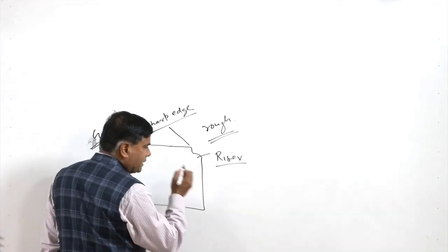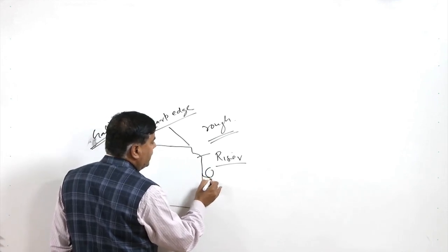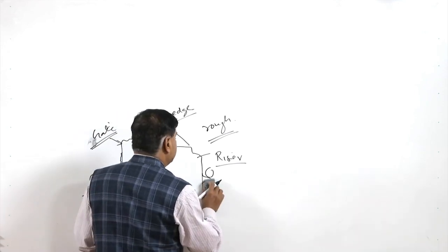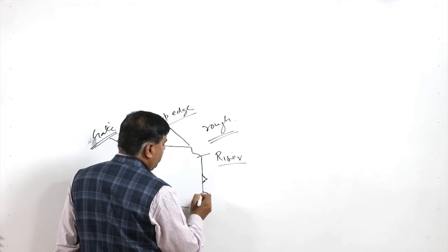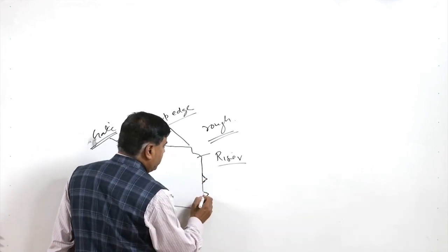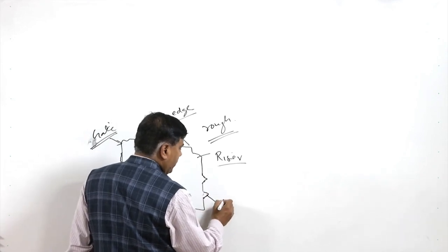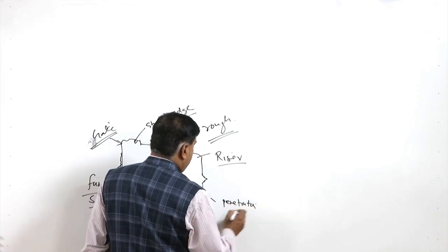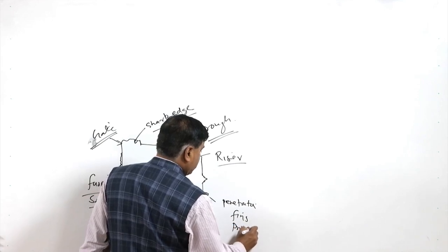If the sand mold had coarse sand particles, then the molten metal will penetrate in those regions, and we will see very fine projections of the metal present in the casting. So, these fine projections also need to be removed. So, these are basically penetrations or fins or projections.